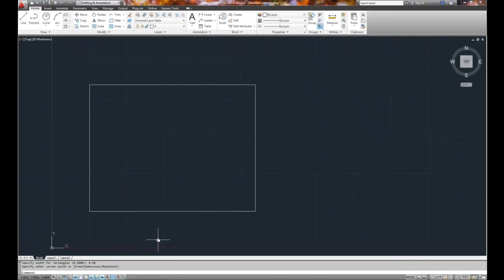So we know that our title block must fit inside that 8.5 by 11 sheet of paper. So I'm going to go ahead and use the offset tool and type in 0.30 and offset all the sides of the rectangle by 0.3. Now, what I found is that somewhere between 0.25 and 0.375, somewhere in that vicinity is where you need to be. We could have gone 0.325. The idea is that you want to make it slightly smaller than the paper because you know that your printer can't print all the way out to the edges of the paper.